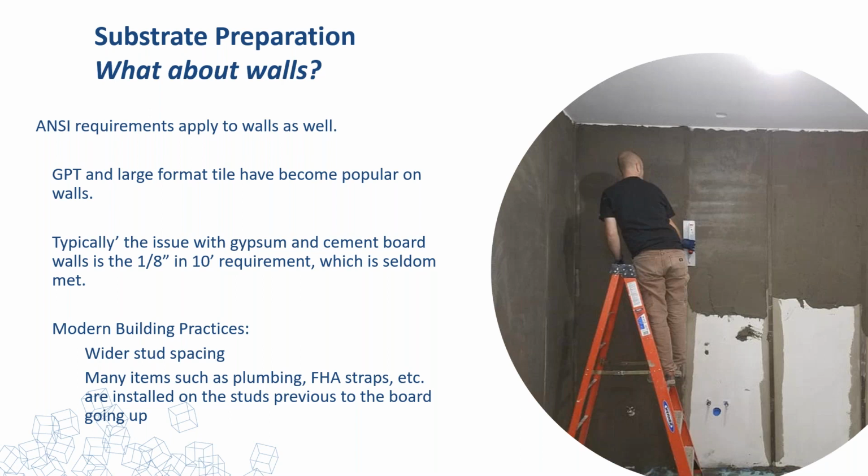Render your walls or patch your walls as well. Most of us have a product specifically for doing that. As an example, we have one that is fiber reinforced. It can go from 1/8 of an inch to 1 1/4 inches, all in one. It's made specifically for walls. It'll bond well to gypsum. It'll bond well to cement board. So if you just have to take care of bird baths in a wall, it's an ideal product for that.